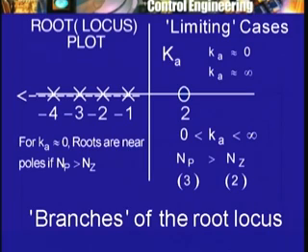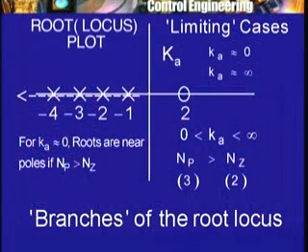Now, there is a simple rule for that, which requires looking at the pole-zero diagram, looking at the real axis, and then observing something. I will not tell you what it is right now, but I will simply give you the rule as it is. In this case, using that rule, this portion of the real axis will belong to the root locus, and I am going to put an arrow on it to indicate that as k increases, there will be a root which will be here, then it will move, that is, for a larger value of k the root will be here, for still another value it will be here, and so on. For very small value, of course, the root will be very close to -1, for very large value of k it will be close to 2. So, one branch of the root locus will simply look like this, and one says it starts at -1 and goes towards 2 along the real axis in this direction.